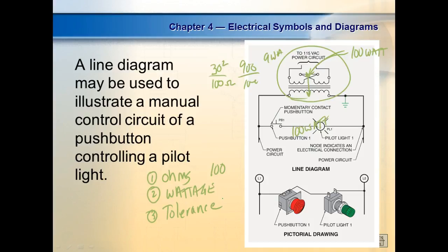So if you needed one with a real tight tolerance, you go 5% instead of the 10. Well, no, we got better percentages than that. So normally what we got is what we call a 4-band resistor. It's number, number, multiplier, tolerance, right? You understand? We have 5-band resistors, which is number, number, number, multiplier, tolerance.